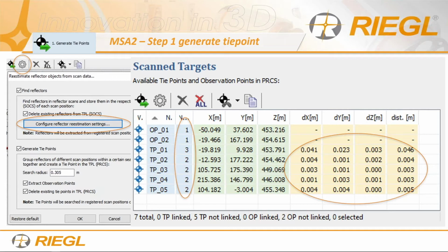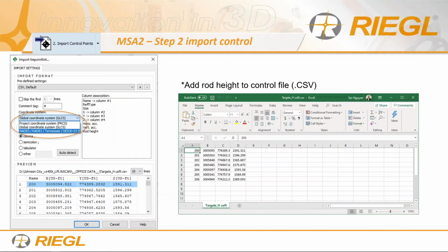You can see TP01 to TP02 to TP05, the deltas on it, it's nearly perfect. You're talking about millimeters difference, right? Which is pretty much scanner error anyways. So this is a very good visual and chart for you to see which survey control is potentially busted, or which scan position that saw the control that the tripod might have moved and such. So it's a very good observation.